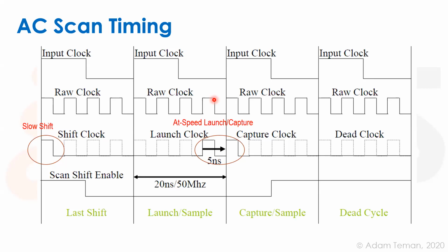Would you have anything to say about that? Yeah, I know it's done. It's quite a common practice. The coverage, usually you make compromises. You're less strict on the coverage of at-speed. You try to apply it to the more critical paths.